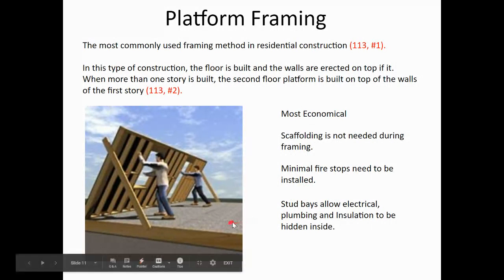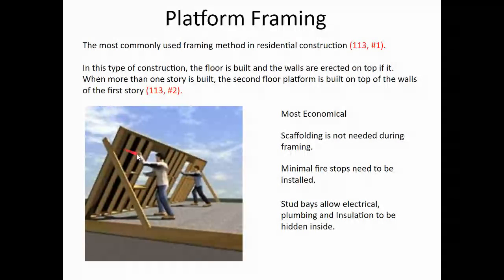So today we do something called platform framing. So what's going to happen? We build a concrete foundation. The next thing we build is this floor right here. The first thing we do is we build the floor. We have a nice big flat area. And then what we can do is we can build the wall. This wall would be built laying down on top of the floor. Okay, so we got a nice big area. It's flat. And then what we do is we just pick that thing up and roll it up into position. And this is what they call platform framing.